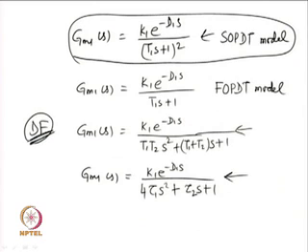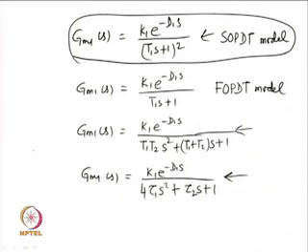So, since we are using describing function and it does not give more analytical expressions, we are forced to choose a simple transfer function model that has fewer unknowns. The number of unknowns in the second order plus dead time model is 3. Similarly, the second one we have got 3 unknowns.